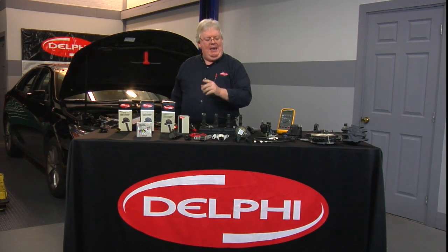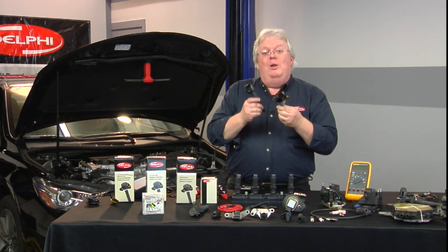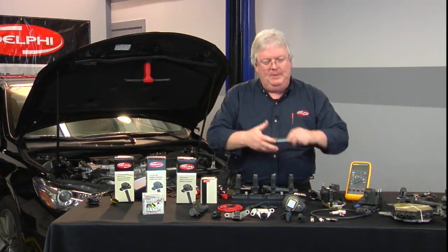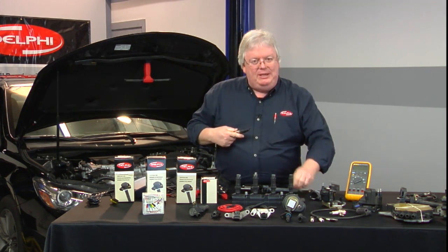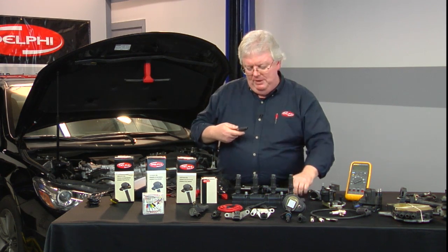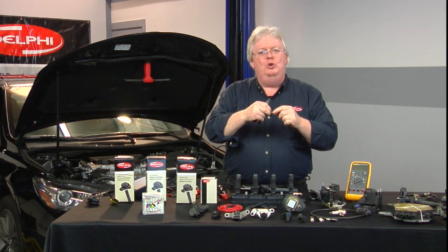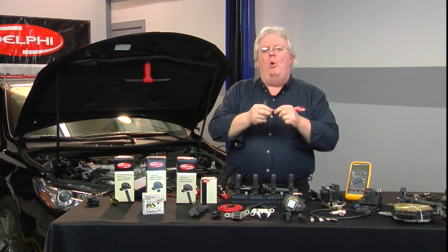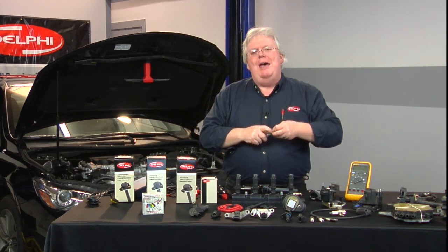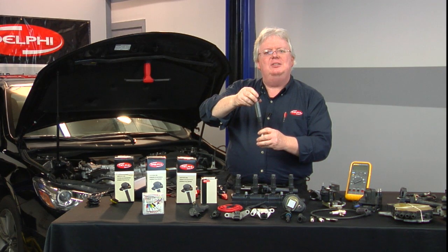The same things that happened with the HEI coil in distributor can happen with Coil-On-Plug when we have an issue with high voltage secondary having a problem, either because of a bad plug, it's essentially open, it's so worn out it might as well be open, or something has happened to the spring, some overheating issue, corrosion, rust, whatever got in here, or somebody left it out, it's the wrong one, you don't have the right application, therefore this is not fitting firmly down in that head on top of that spark plug.